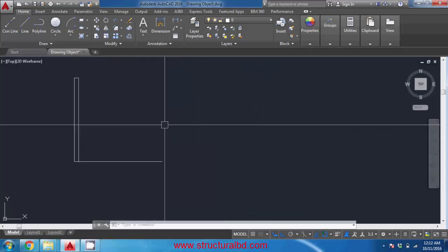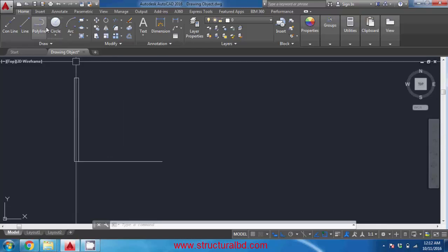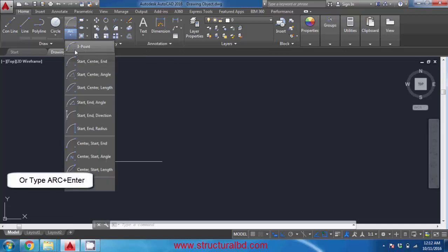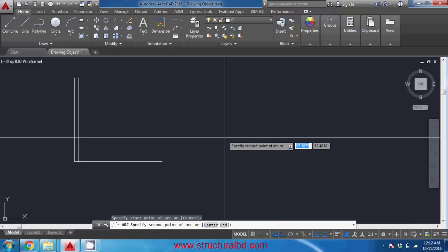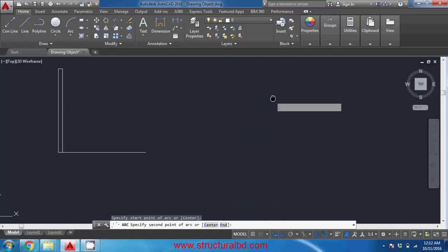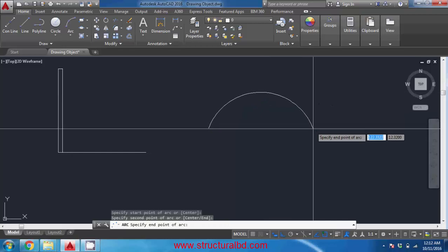In this video you will learn how to draw arc, circle and ellipse. Start with the arc command. Go to ribbon tab Home and click the 3-point option. Specify the first point anywhere in the space, then the second point, and click here to specify the end point.